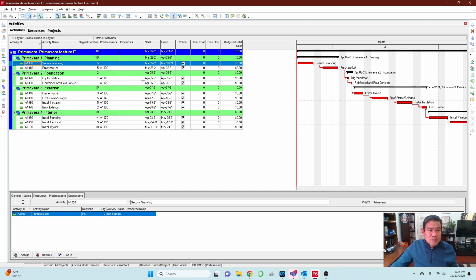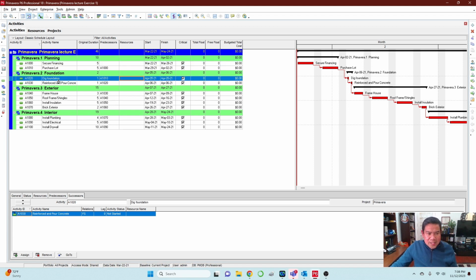So what to do is go now to that particular task or activity where you want to add your resources. In this case, again, there are two possible ways. You can go into your resources icon on the right navigational toolbar, or you can add this resources column, making use of this particular icon here on the standard toolbar.